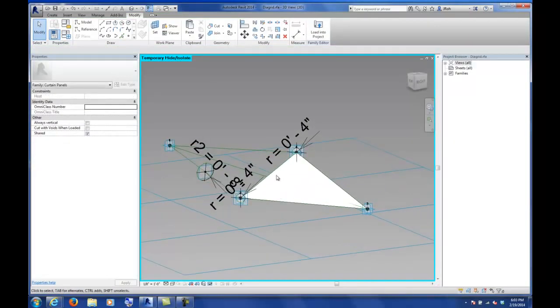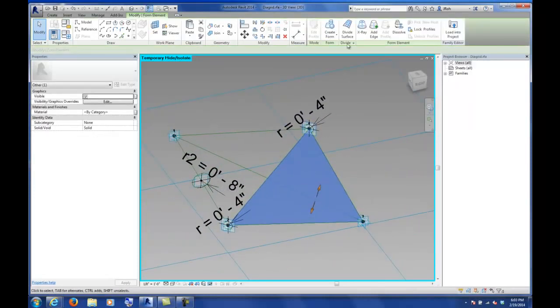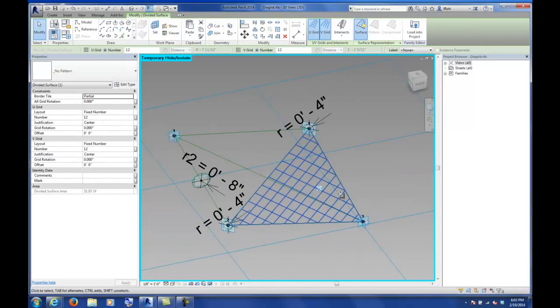I can take this even further by selecting that particular surface and divide that up, and you could apply more components to that, and then embed that within your other component. I'd advise you not to divide it too much because you can really get some pretty detailed, intricate components that start to take up a lot of memory.